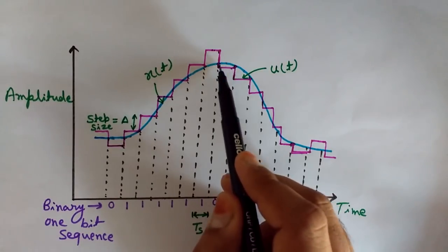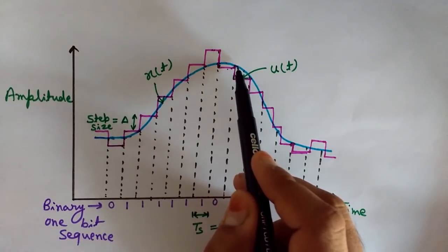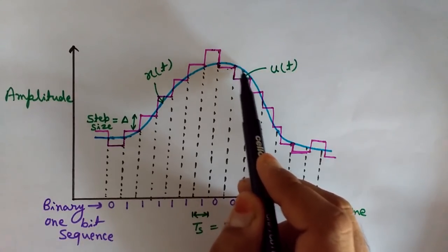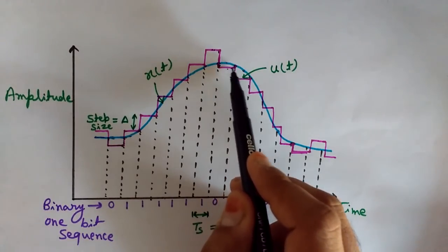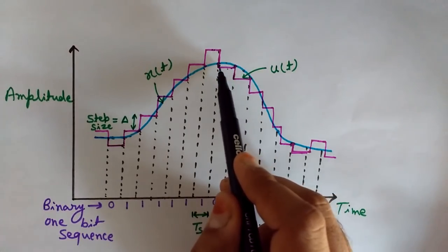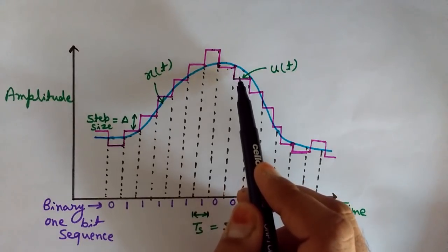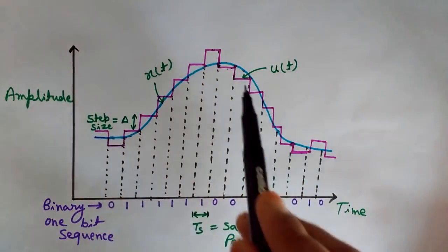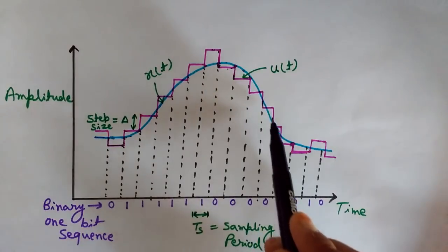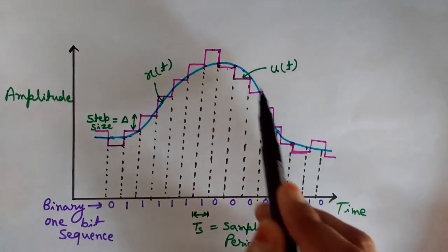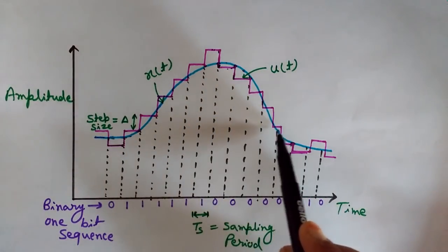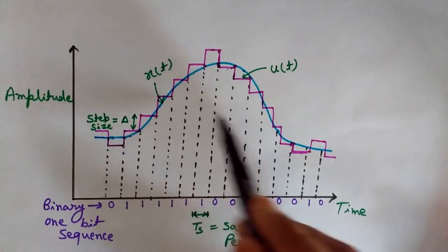So now look at this and the next signal. If you compare this, then again this sampled signal value is lower than this last approximated signal. So we again decrease it, and since it is a continuously decreasing part of this analog signal, this keeps on decreasing. So what rule are we following here?